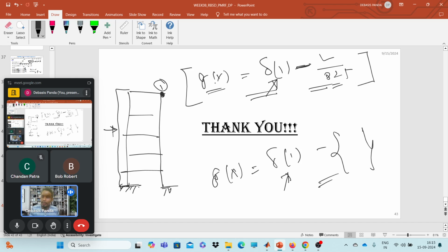Clear? So we will solve some problem. This is actually rich, but you can solve it if you have your model with you. So we can directly link it with MATLAB, and we can generate this number of samples. Like for example, if I want to get the displacement of this node, what I need to do, I need to generate the 100 samples of loads, and I will apply this. And every time I am applying this load, I'm storing the results of this displacement. So I have 100 or 1000 samples of displacement. Now check with your limit state concept.